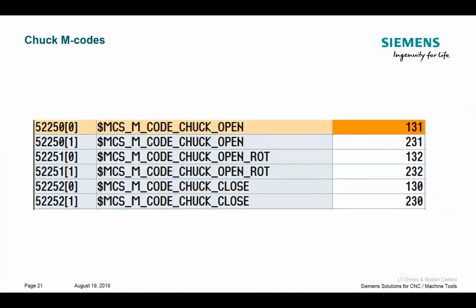Can I open the chuck when it is not spinning, but also can I open the chuck while it is rotating? Generally speaking, you don't usually want to open a chuck while it's rotating, but if you're going to do some kind of live transfer, or a part-off operation, chucks have to be spinning. So here, I'm going to use a combination of 4 M codes.